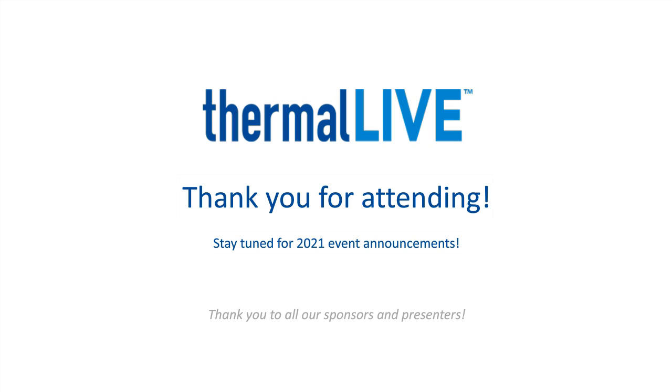That's a good question. We typically would recommend filtering out particle sizes that are about half the average pore diameter. As you can imagine, there's some distribution of pore diameters within the foam, and so for example, for a 40 ppi foam, the average pore diameter is about 1 millimeter. So we'd want to filter out at least anything bigger than 0.5 millimeter. And that's for uncompressed foam.